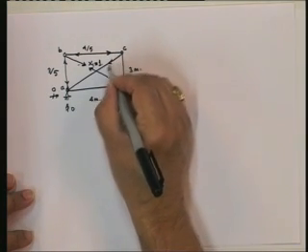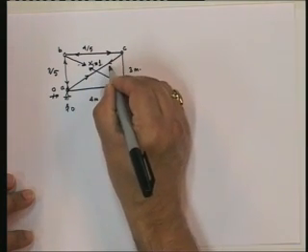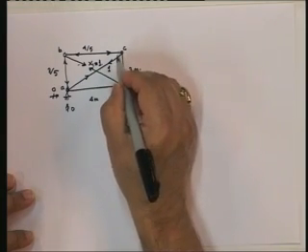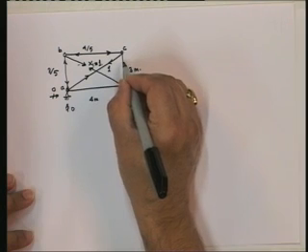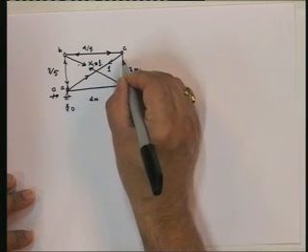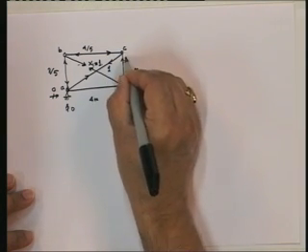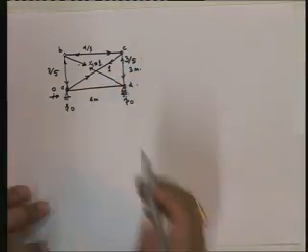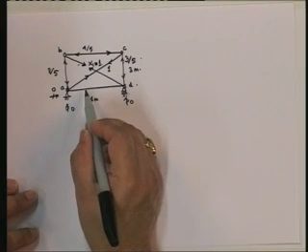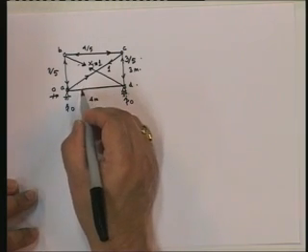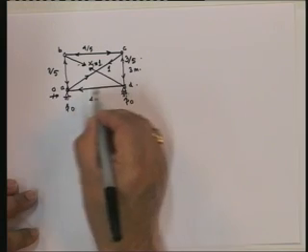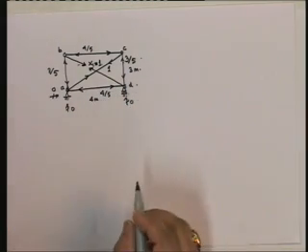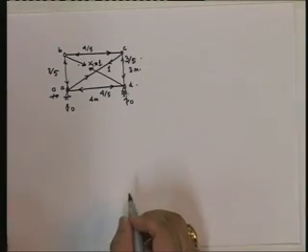So if you do that, you will see that this works out to 1. Once you do that, then you can find out what is the force in this member, because the vertical component of this is going to be equal to this, and that way I am just writing down the values. You should be able to find them out. What about the force in this member? You will see that this will turn out to be 4 by 5.